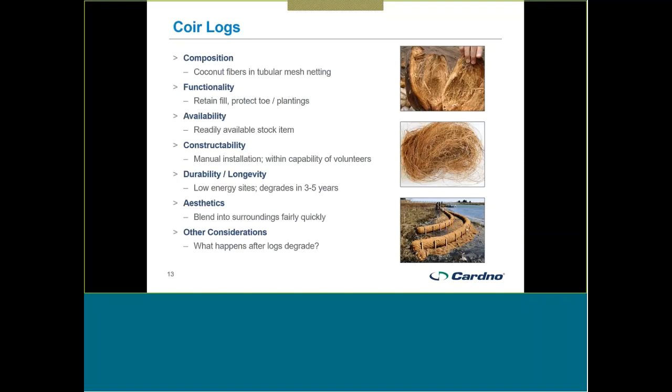And they're really designed to establish, as you see in this picture on the lower right, the toe or the front leading edge, channelward edge of a living shoreline, and then they help retain fill. So typically sand would be backfilled behind here, and this is going to help keep that sand from just washing out every time a wave laps up on here and retreats back offshore.